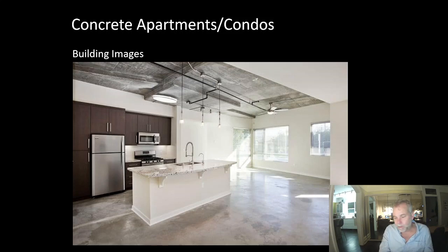Now, we talked about STC rating, that's sound transmission class, terrific, no problem here. But impact noise, I don't remember what rating that's called, this is problematic. Somebody drops a glass, and the person down below is going to hear it as though it was in their own kitchen.